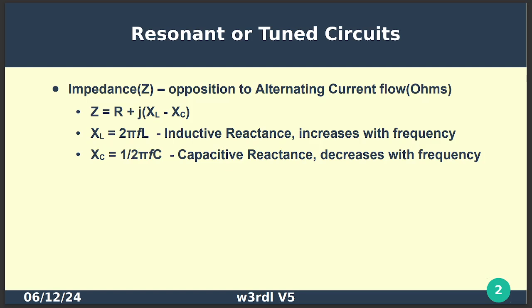So inductive reactance increases with frequency, and capacitive reactance decreases with frequency. This will be used later on when you start trying to plan out your antenna, because certain things can happen if you add a capacitor or add an inductor.